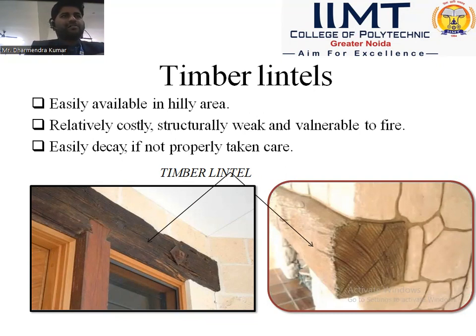Timber lintel is also easily available in hilly areas, but it is relatively costly, structurally weak and vulnerable to fire. This is a big disadvantage of the timber lintel. Because it is very weak and vulnerable, it decays very easily if proper care is not taken.